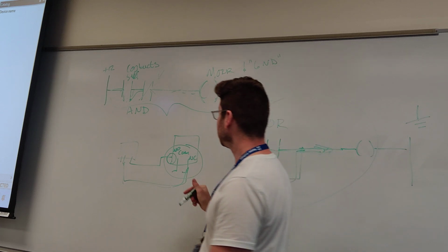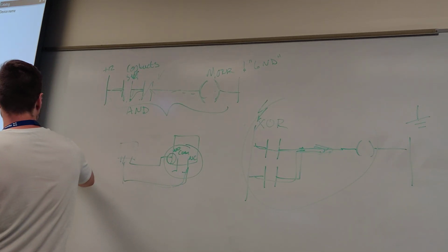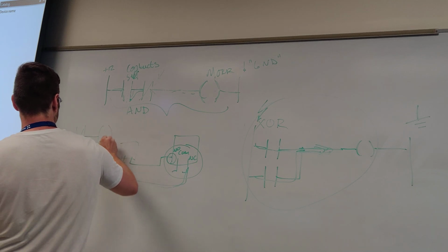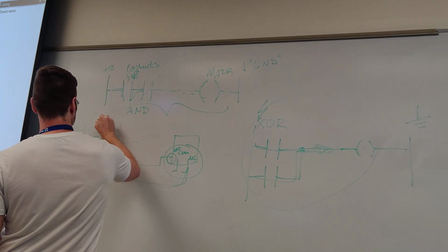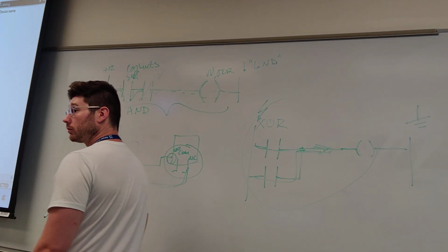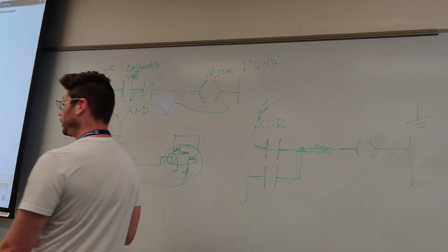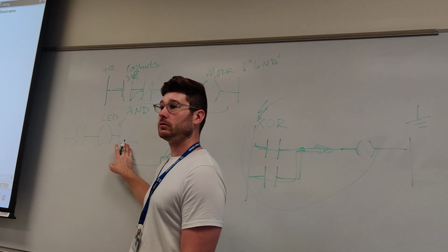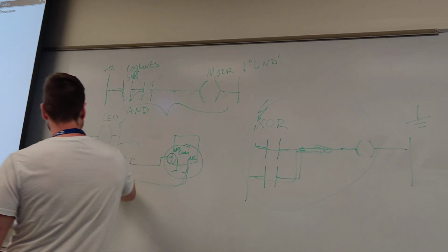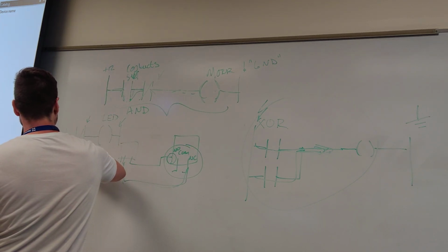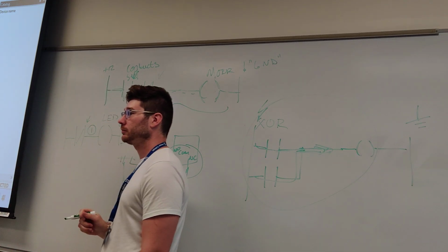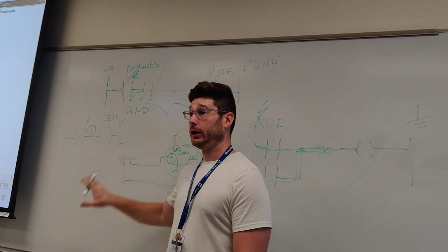In this situation, where we have a normally closed contact attached to an LED coil, like that, this LED will always be shining. If no finger was pressing this button, it would be on by default. Another way to think about this is that these contacts, when we negate them, output a logic 1 by default.